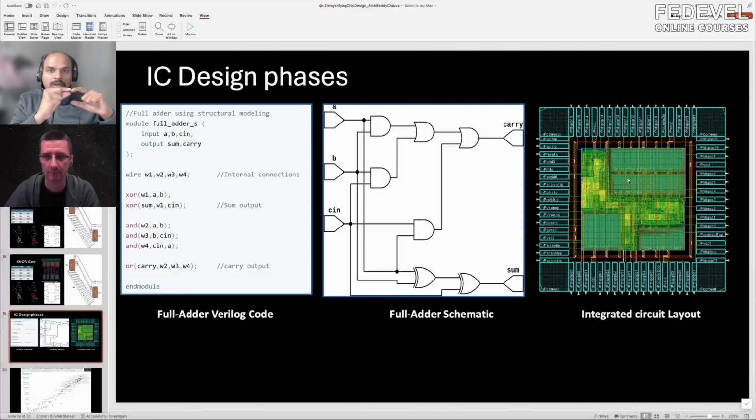So the electron reaches from source to destination much faster than with a bigger transistor, and your performance is much higher for the smaller devices. That's one way you can increase the performance. At the same time, you also want to reduce the power, and it requires less power if you lower the voltage.